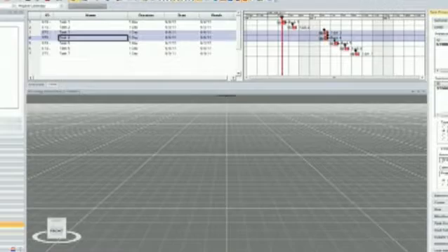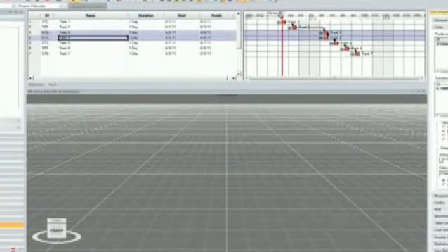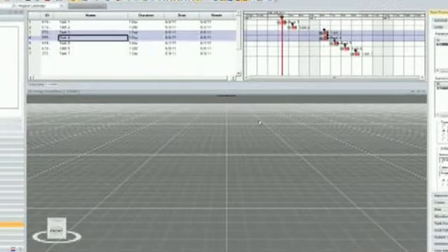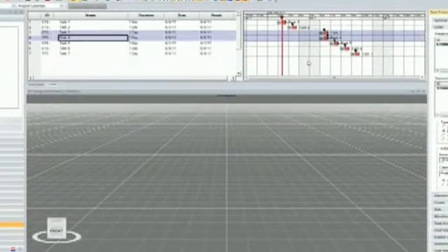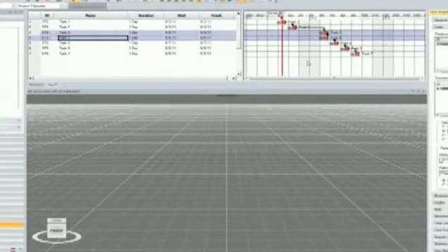So you do this iterative process back and forth, back and forth, back and forth. Well, in Synchro, we control the schedule. So I take the schedule from Primavera, I bring it to Synchro by a push of a button. I can now change my logic in Synchro, and then I can synchronize to Primavera, and it makes all my updates right into Primavera automatically.